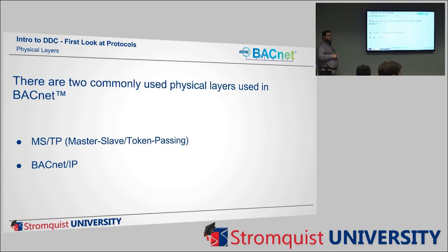Can you think of a scenario where that would be desired? An advantage of it being easier to put stuff on different buses and make them talk is that, and we'll get into this with the different types of media that you do BACnet on, it's a lot easier to go from 2-wire BACnet to IP than it is in LONWORKS.